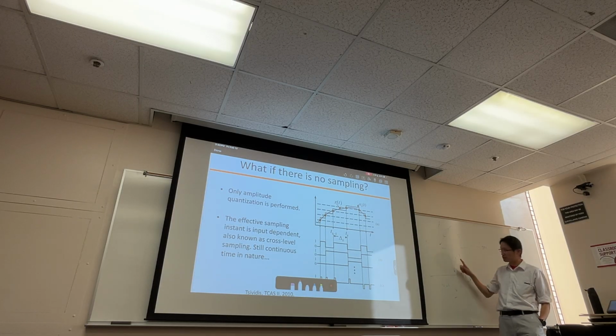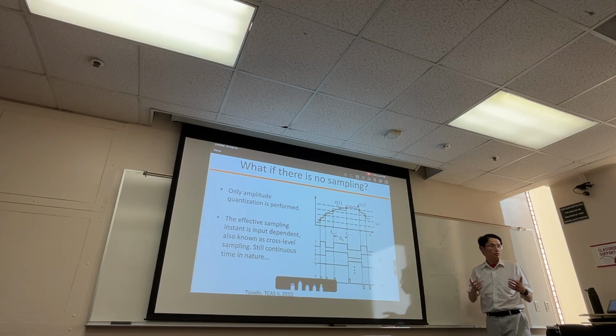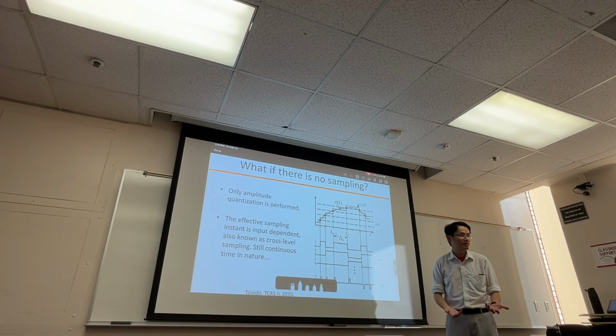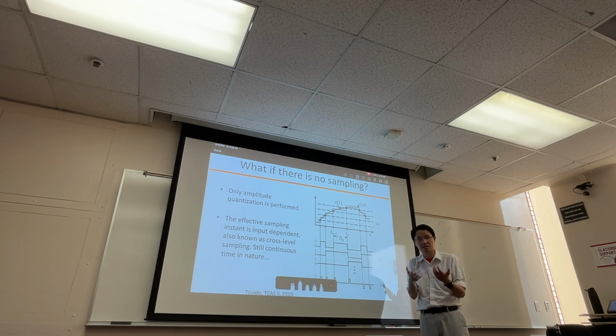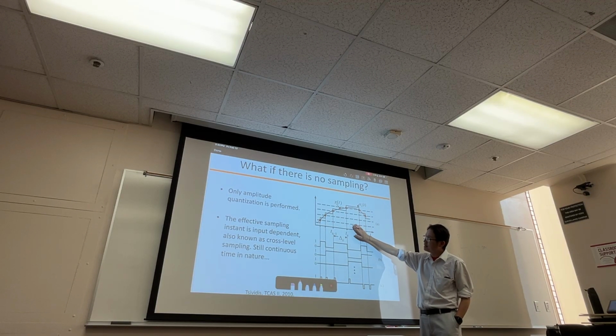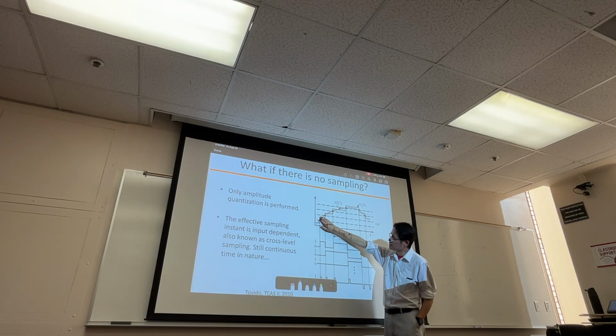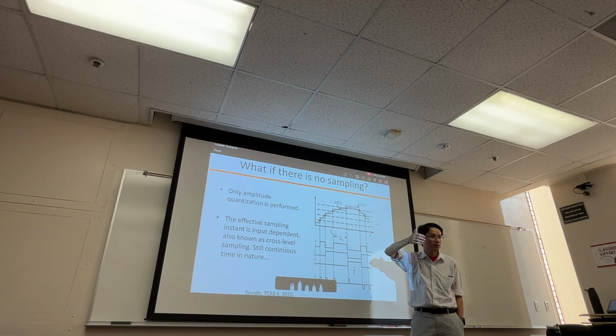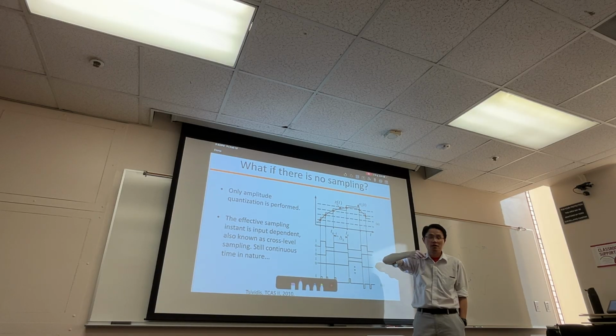This ADC needs a clock to sample, right? Here you just let it run. You cross the level, whoop, you change the code and you do something. So that ADC itself is clockless. Sometimes they also call it a clockless ADC. And then you have all these different properties, and like I said, the sampling times are signal dependent because it really depends on when you actually cross a particular level.